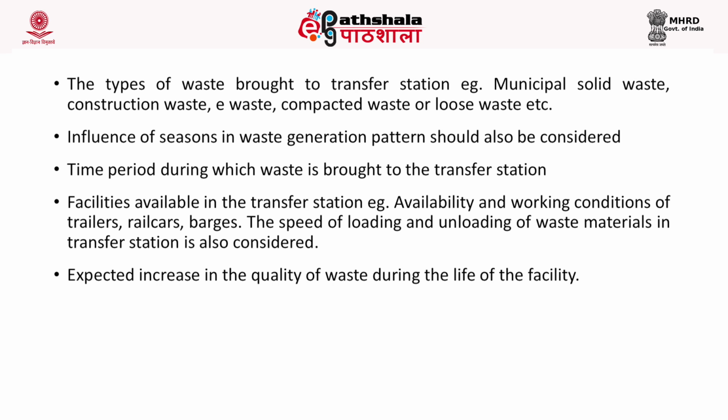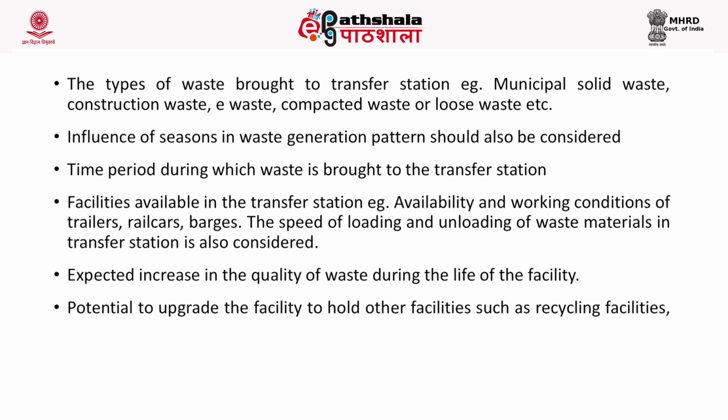Third, changes in the population, segregation pattern, recycling programs, peak flows of waste, types of vehicles delivering the waste, the nature of waste, for example, from which source the waste is coming, like the municipal waste, construction waste, e-waste, and so on. Influence of seasons, then time period during which waste is to be brought to the transfer station, then facilities available in the transfer station, example, the availability and working condition of trailers, rail cars, barges, etc.